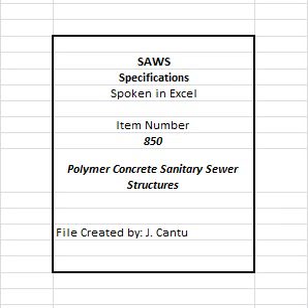5. Sewer structure ring and cover castings shall meet the current requirements of AASHTO designation M306-10 and must be listed in most current SAWS APL. 6. Compressive strength. Polymer concrete shall have a minimum unconfined compressive strength of 9,000 psi when measured in accordance with ASTM C497. 7. Polymer concrete mix design shall consist of thermosetting resin, sand, and aggregate.